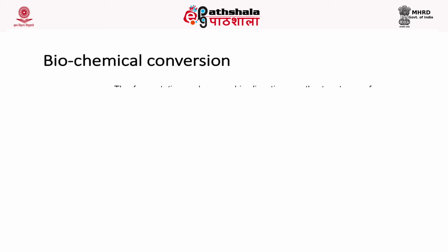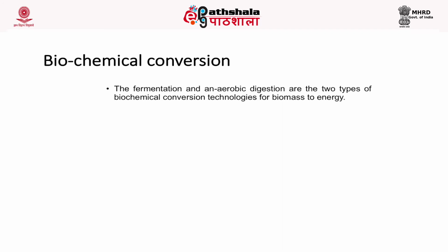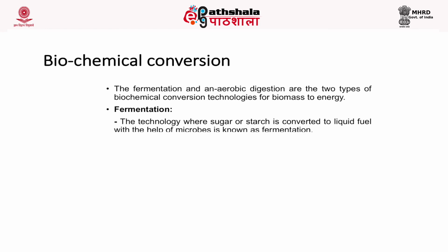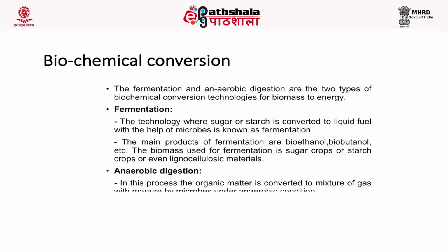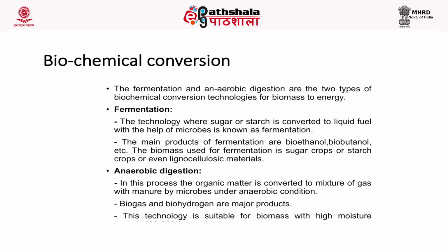The biochemical conversion includes fermentation and anaerobic digestion. Fermentation is the technology where sugar or starch is converted to liquid fuel with the help of microbes, especially yeast. The main products are bioethanol and biobutanol. The biomass used for fermentation can either be from sugar crops or starch crops, or even lignocellulosic materials can also be used.